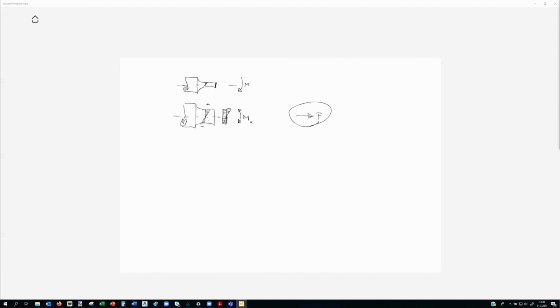Yes, I guess I confused the bending moment amplitude with the bending moment itself. So taking into account that we know the R and we also know the amplitude, we can calculate the maximum absolute value of the bending moment. We can also calculate this maximum value sigma max, which would be sigma bending plus sigma tension, if we put it like that.